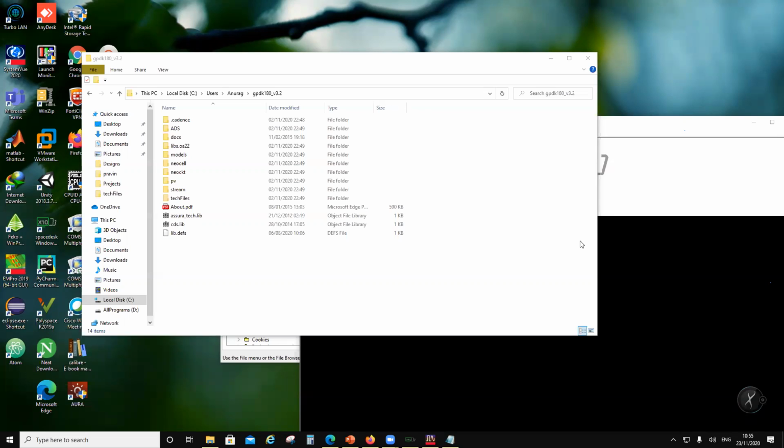There are models for passives also, but circuit simulation means we can use models for active devices, and then take passives from EM simulation and put them together as one simulation space. So that's the two-step solution: take the passives, simulate them in EM, get the S parameter files, put them into the circuit simulator, and simulate them along with the actives.